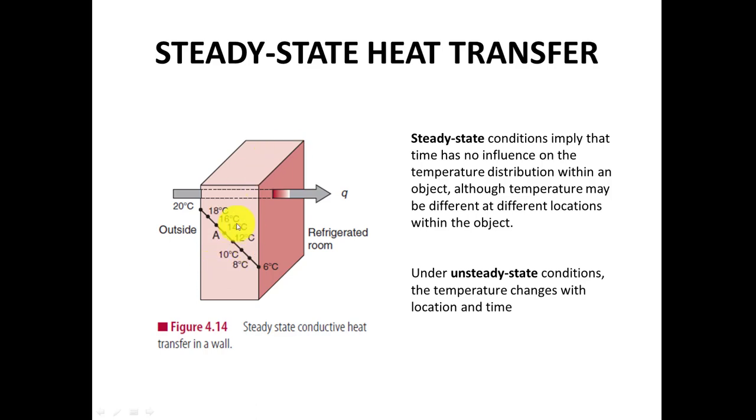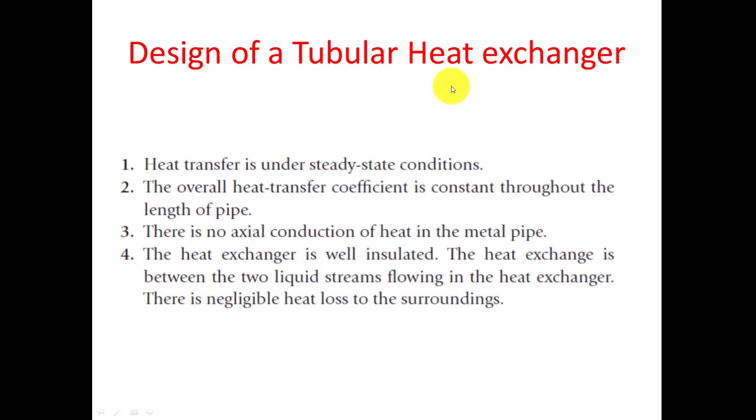If we consider this fluctuation, then calculations are very tedious. So to simplify, and just as an approximation, we assume steady state heat transfer conditions. That is the first condition for the design of tubular heat exchanger. Second, the overall heat transfer coefficient is constant throughout the length of the pipe.